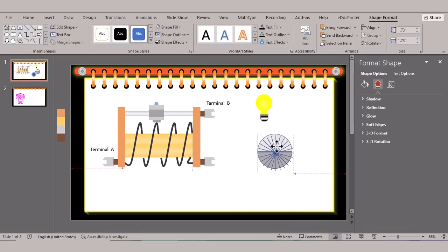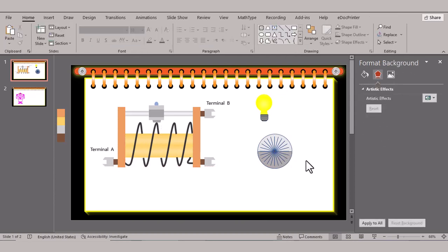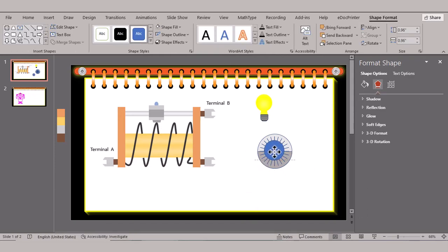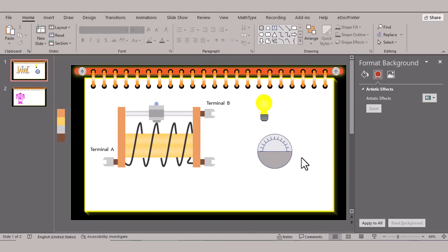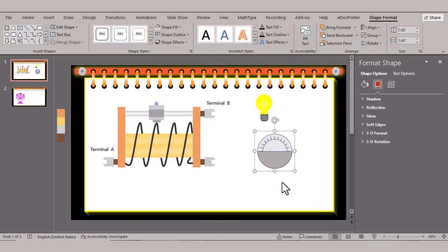Ammeter, instrument for measuring either direct, DC, or alternating, AC, electric current, in amperes. An ammeter can measure a wide range of current values because at high values only a small portion of the current is directed through the meter mechanism. A shunt in parallel with the meter carries the major portion. An ammeter, abbreviation of ampere meter, is an instrument used to measure the current in a circuit. Electric currents are measured in amperes, hence the name.